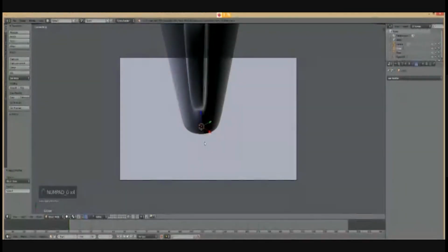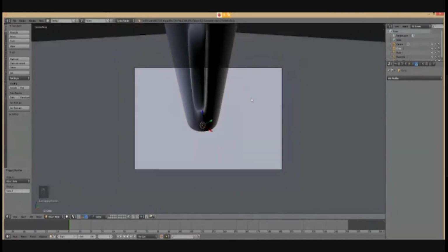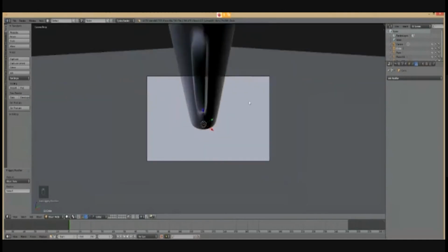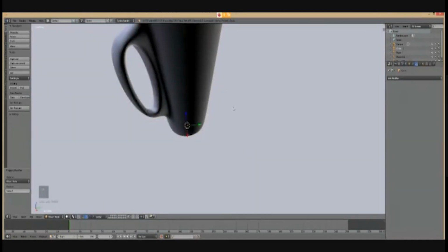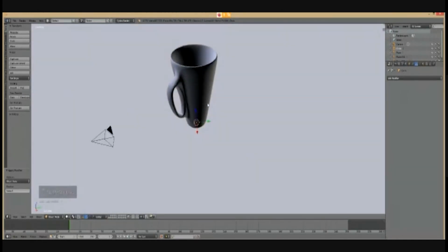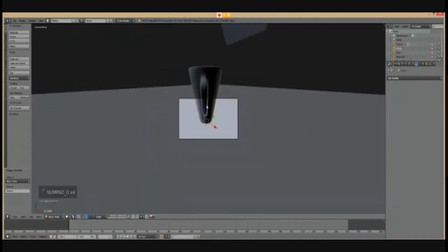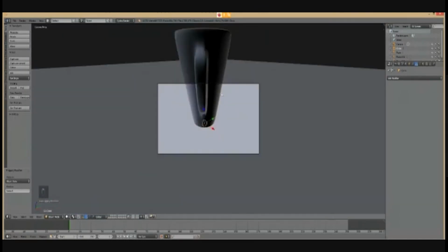This little box over here, right, within the camera view, when you render, all that is within this box is what is going to render. So it's very important that within this camera box, you have whatever it is that you want to render. Right now, our entire coffee cup is also not there. However, once I have this camera box, if, for example, I try to zoom out, or I try to rotate, or try to move, it automatically comes out of the camera view. If I try to zoom out or zoom in, I'm not able to change my camera essentially.